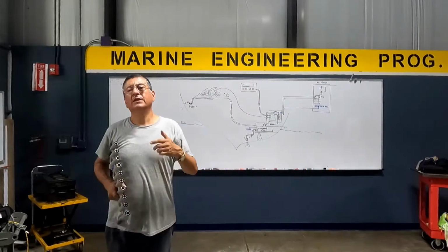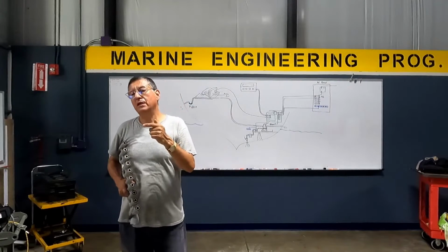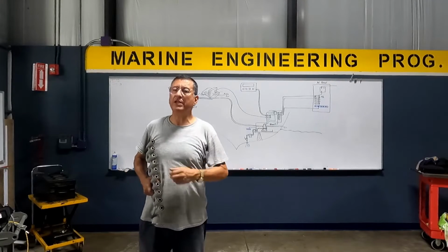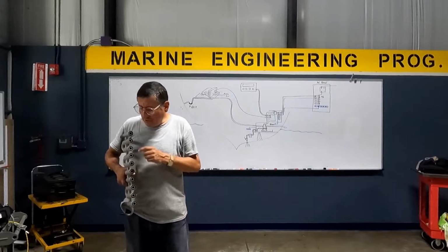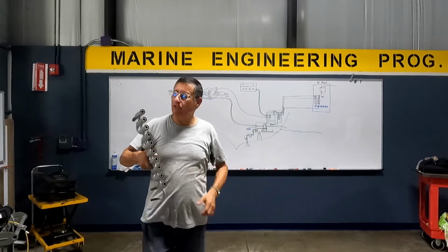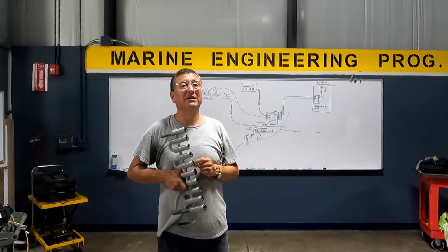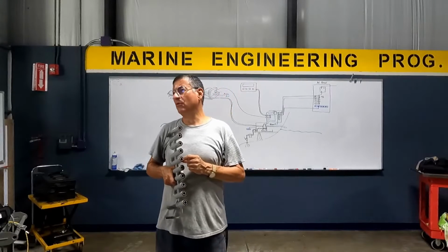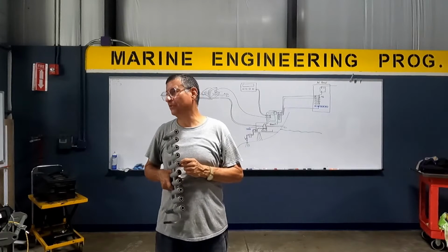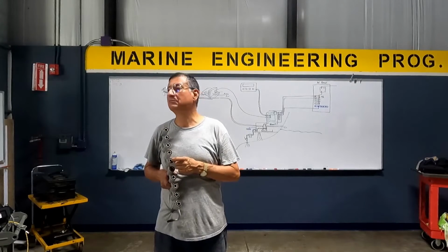Is it possible? It's a great question. Is it possible that the salt water be mixed with the refrigerant? Only if it's broken. It's possible if those pipes are cracked internally. But this is not common because the quality of the material is a copper nickel alloy, you remember? It's a 90/10. It's a great alloy. It's practically zero the possibility that those pipes are cracked and the salt water penetrates the coolant.